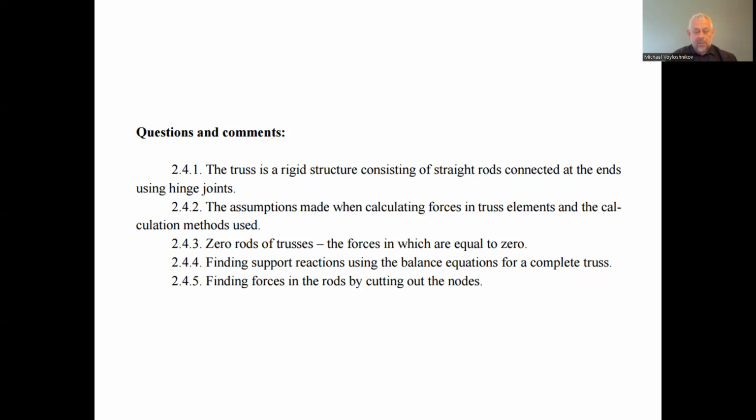Finding support reactions using the balance equations for the complete truss. We can consider, if the truss is statically determinate, that we can find the support reactions considering the balance equations of all forces and directions loaded on the truss.